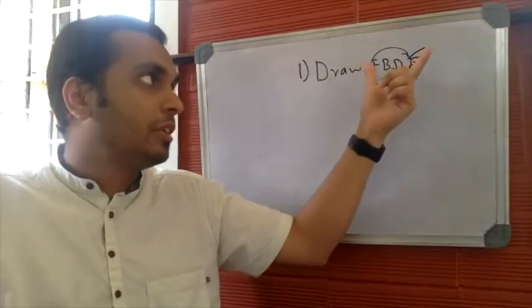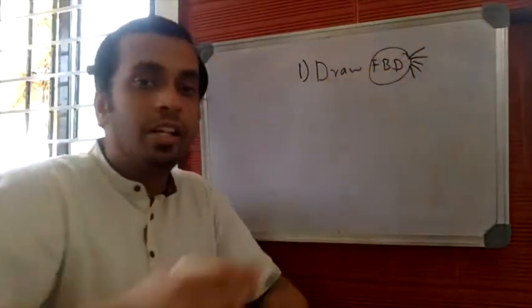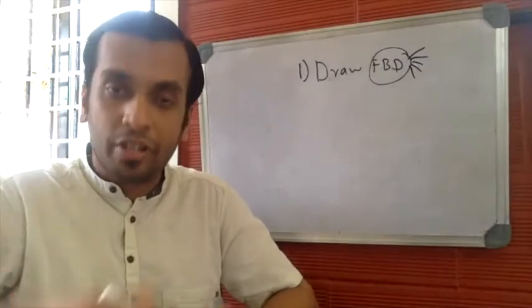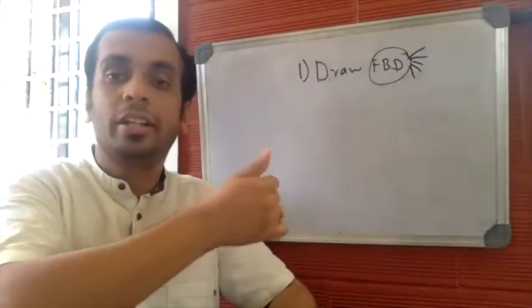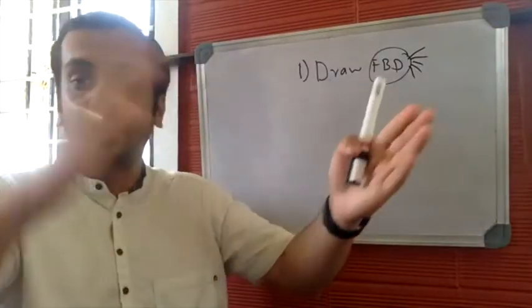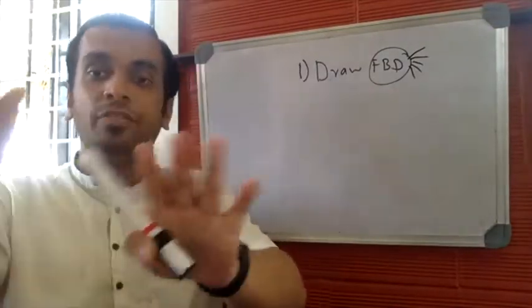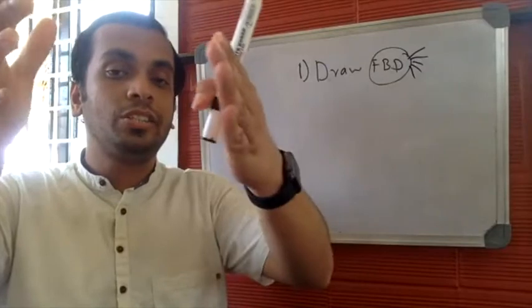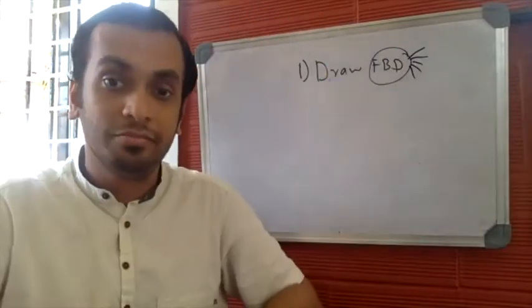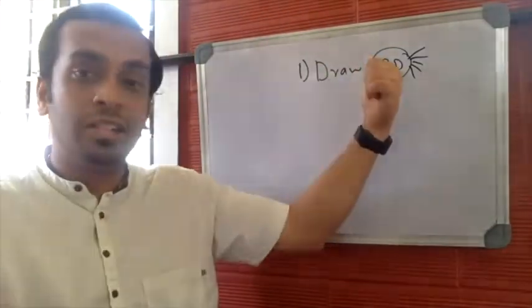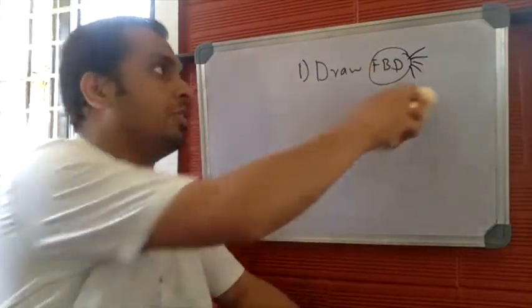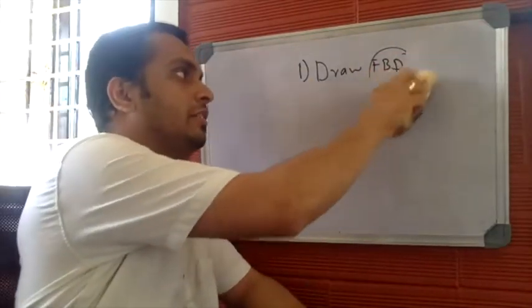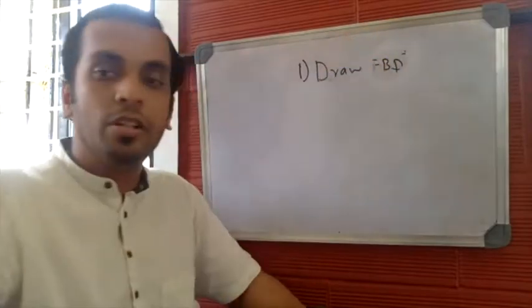You'll be locating the center, then drawing the coordinates, marking the self-weight, marking the normal reaction, marking the tension through the string, then finally you'll reproduce the coordinates along with the forces systematically. You bring all the forces to the center and you'll draw the free body diagram. These are the steps involved in drawing the free body diagram. But here, to solve the numericals, the first step is to draw the free body diagram.